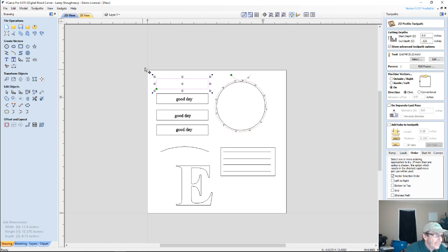again. I can actually draw out my table, I can lay out where my boards are, I can have my designs on my boards, and I can say I want to do this one first, this one next, this one second, or this one third and fourth. And it will cut those boards, and as it cuts them in order, I'm able to take those boards off the table and clamp another one in its position. Now I have a jig with a specific location that every board goes into.